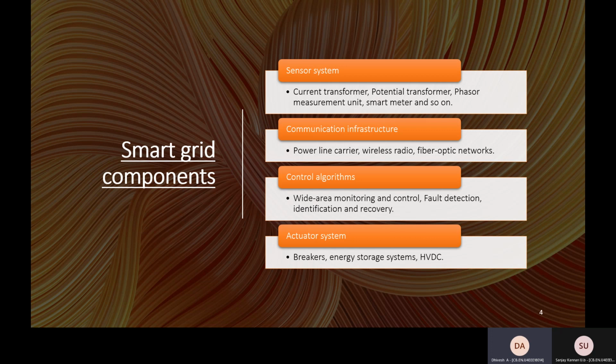source. The transducer generates electrical signal based on phenomena such as power line voltage. The microcomputer processes and stores the sensor output. The transceiver, which can be hardwired or wireless, receives a command from a central computer and transmits data to that computer. The power for each sensor is derived from the electric utility or from a battery.